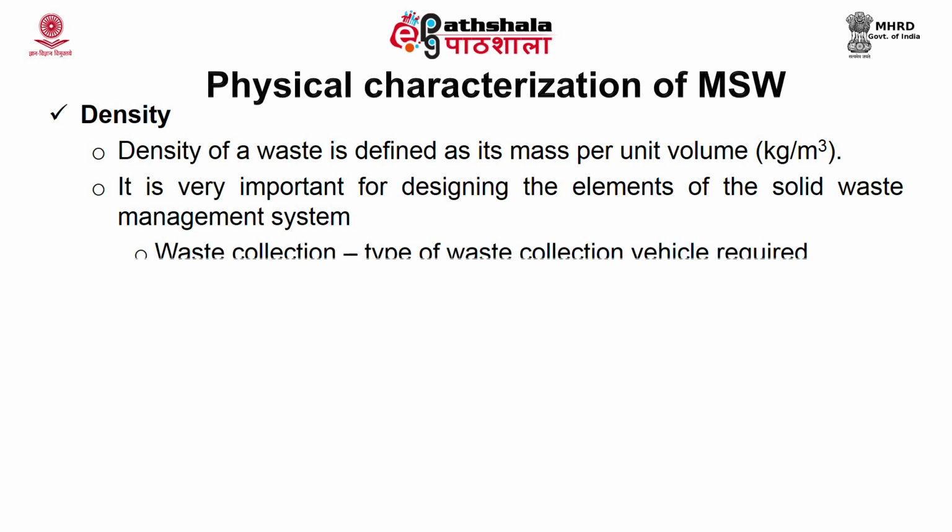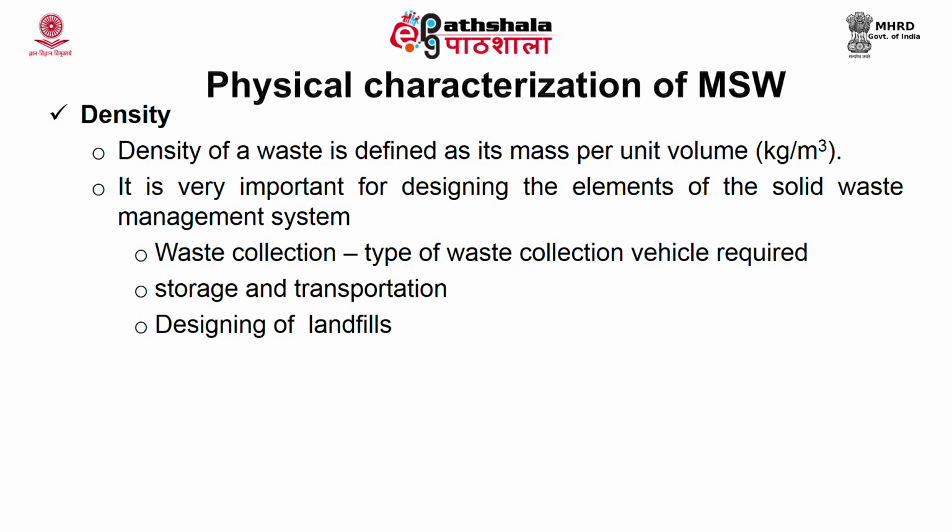It is very important for designing a solid waste management system, starting from your waste collection to decide the type of waste collection and transport vehicle. It will also help you to decide the type of storage container required for storing the waste. Also, density is required for designing the landfill structure.